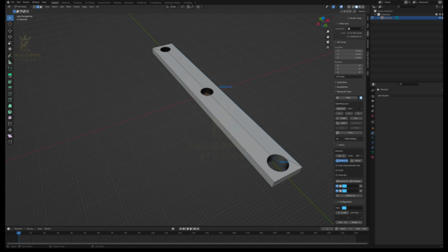Let's go ahead and use the Extrude tool. It's probably the most common tool. So first we'll go into face selection mode. Let's select the face first, and then go to Extrude. Now you could either pull out this object manually, or what I find to be easier and much quicker is, instead of using the Extrude tool, we could use the keyboard shortcut, which is E for Extrude.